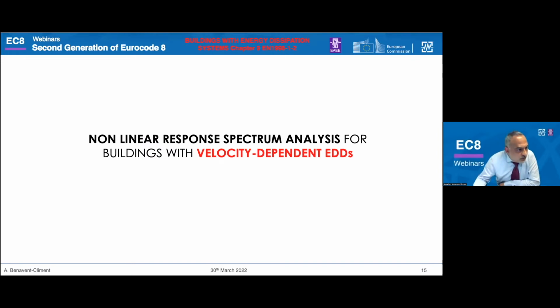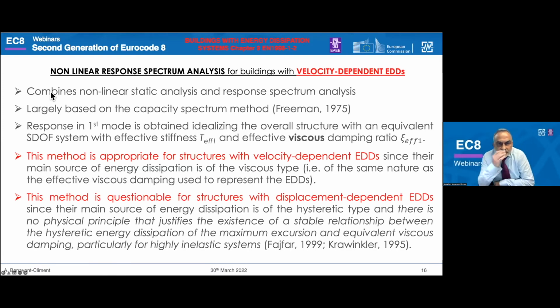Now I would like to give you some background information about the nonlinear response spectrum analysis that is used for buildings with velocity-dependent dampers. The nonlinear response spectrum analysis is a combination of the nonlinear static analysis that Matthias has presented before and the response spectrum analysis. It is largely based on the capacity spectrum method proposed a long time ago by Freeman.